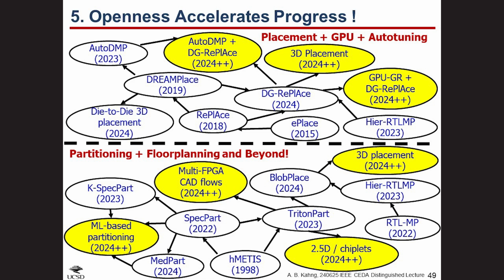But as you see, if you're up close, there's a 3% variation, 3.4% variation in the effective clock period, 38% variation in leakage power, 11% in standard cell area, 11% in total power. That's like an entire node of chaotic variation. If you can afford to make a lot of runs, that helps to denoise this.